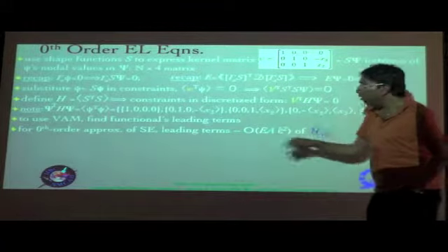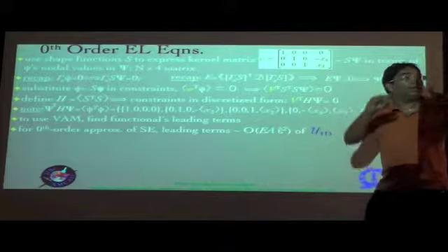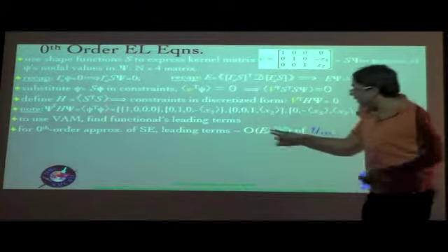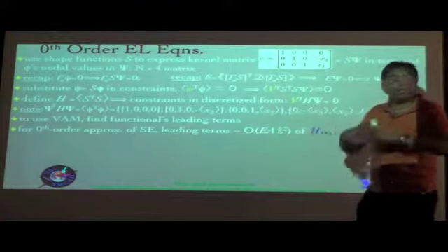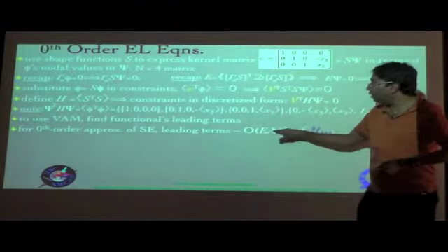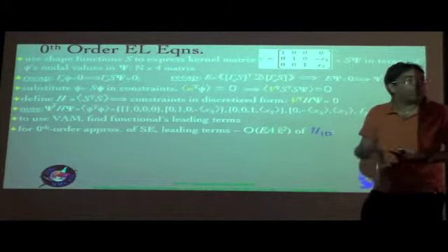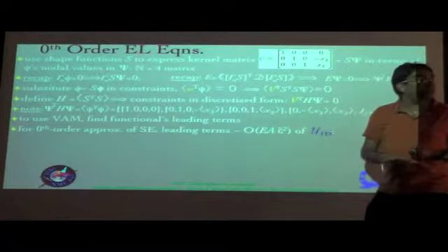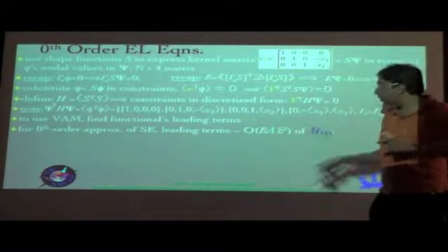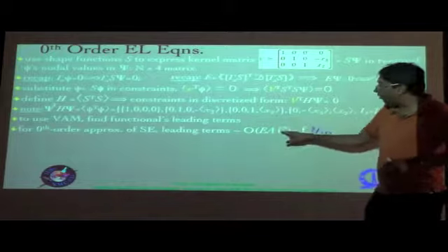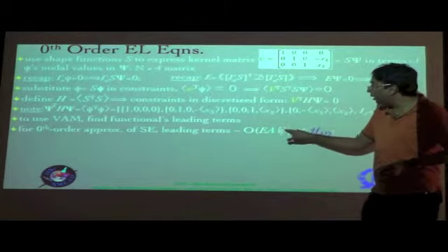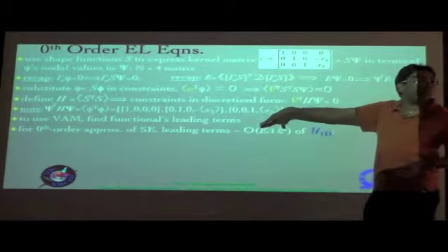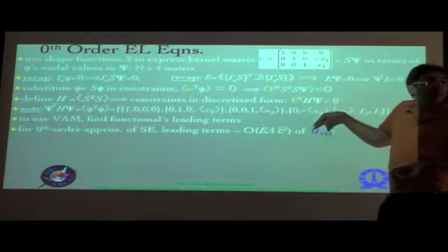This is just the order of magnitude of any quantity within that flowery D, which is the material stiffness matrix, right? And of course there's an integration over the area, and therefore this is A. For a class R beam, it would just become small a squared. And then, because it's quadratic in the strains and we are taking only the leading order terms, the leading order terms in the strains will be of the order of epsilon hat, and because it's quadratic in that, it is of the order of epsilon squared. So this is the order of magnitude of the terms we have to retain in U1D.